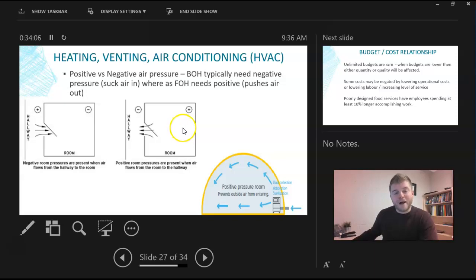Immune-compromised people would want a positive air pressure in the room because they don't want any outside germs, traveling germs, people walking in the hallway. So immune-compromised people would have a positive airflow, so their air in this room would be pushed out versus the outside, unclean, unfiltered air coming in.